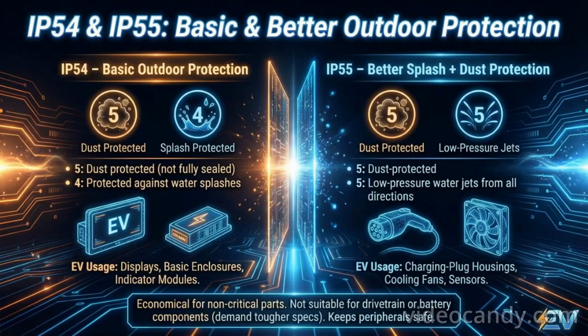Everyday IP levels are IP54 to IP55, which are street-friendly shields. IP54 grants dust-protected status and splash resistance, adequate for external displays and basic enclosures that never face pressurized water. IP55 adds defense against low-pressure jets, suiting charging plug housings, sensor pods, and cooling fans mounted outside the cabin. Neither rating seals completely against dust, so drivetrain and energy storage parts demand tougher specs, while these economical codes keep non-critical peripherals safe during routine rain and washdowns.